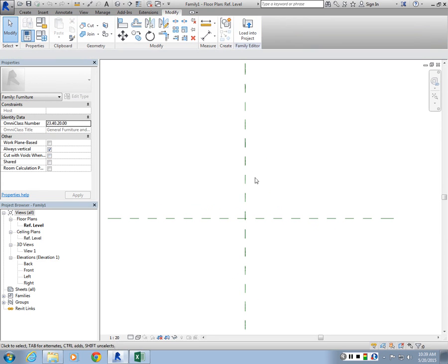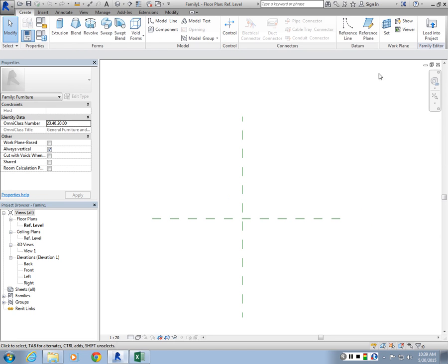And normally you would place the center, or the centroid of the furniture, you will align it to the origin of these axes, and then for the dimensions you will just offset these axes and create references. And those references are mostly the reference planes that we're going to use, so that we kind of use them to stretch our models. So I'll show you what that means.